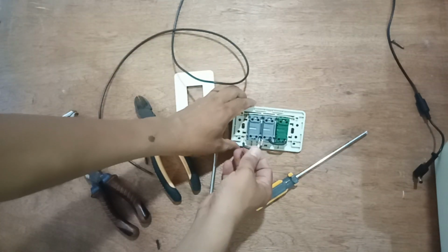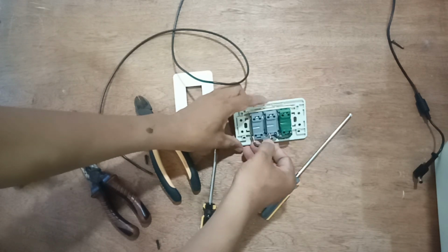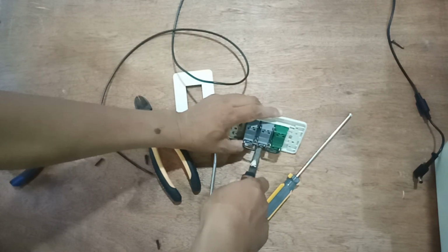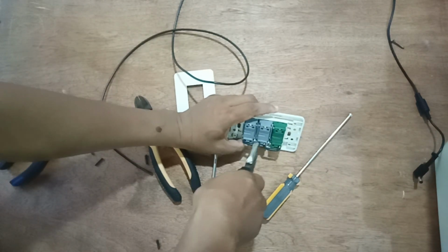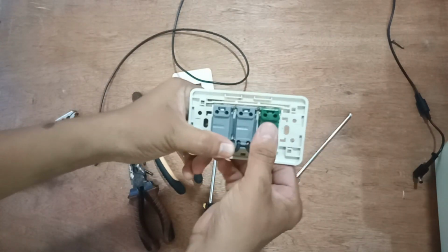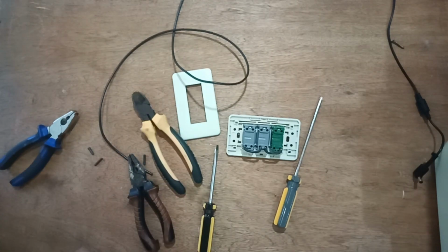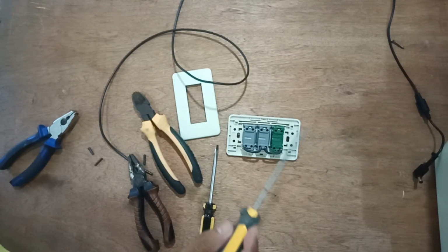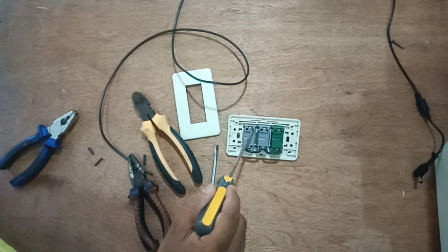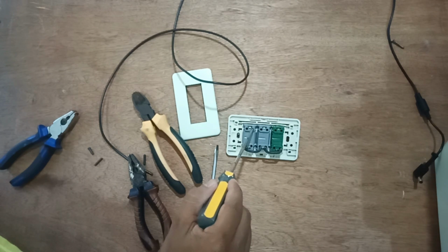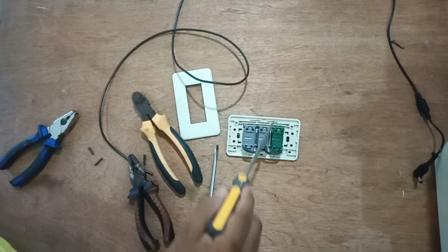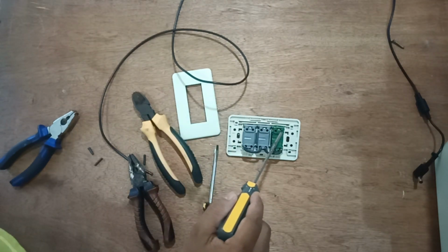then jumper over here this way. Okay, so I hope you can follow, guys. This way, push the other side, push also, and then bend the wires right here. So that's how we are going to jumper. Meaning to say, your common terminal would be right here, or even this side. Then the other side would be your distribution line going to the load, bulb A. Second is for bulb B, and the other side is for bulb C.